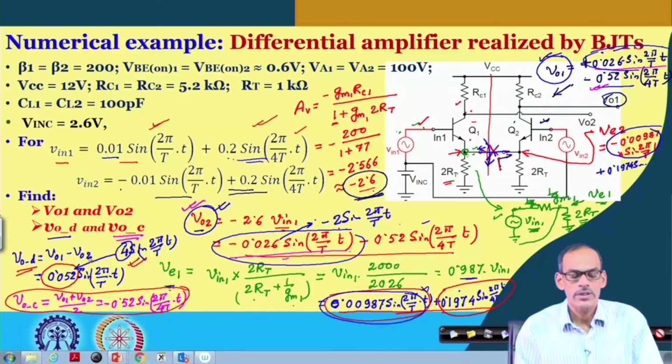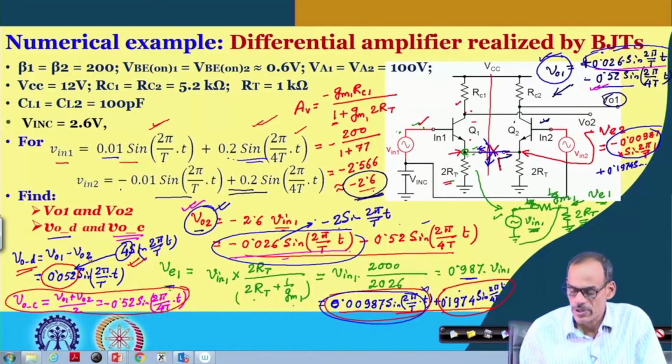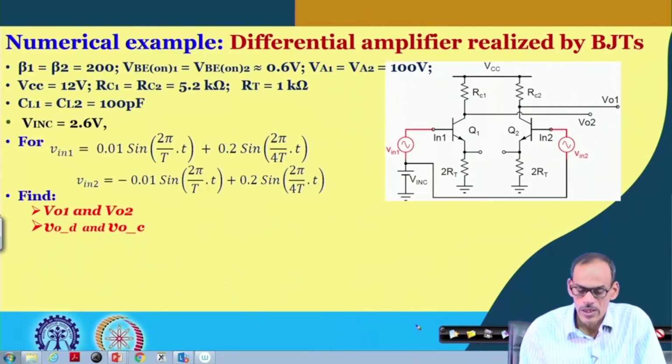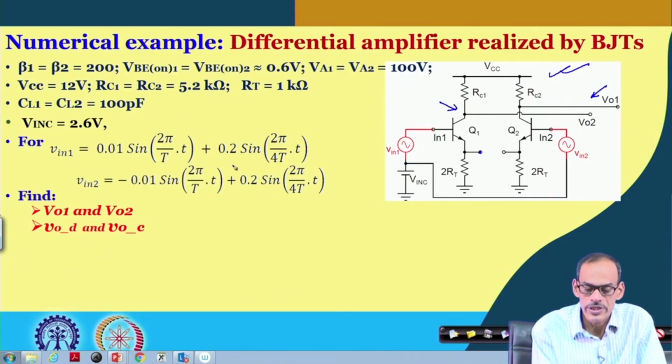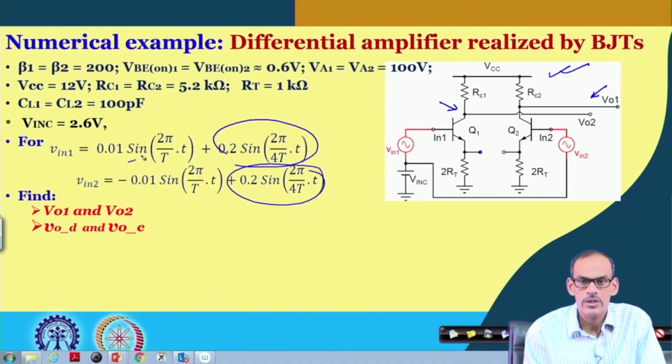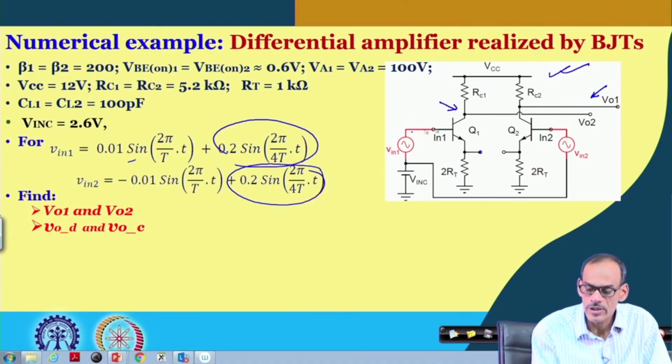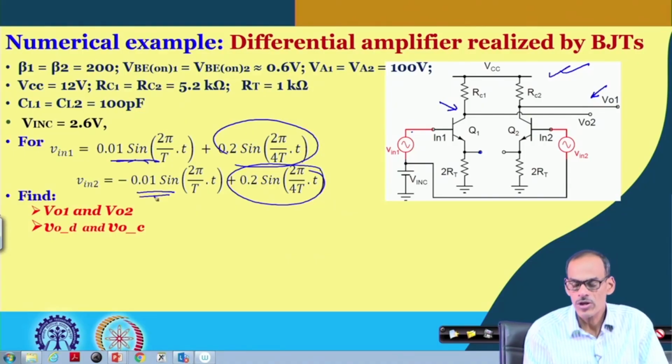In fact, in hardware you can make this experiment, namely you can construct this circuit, and if you keep it open and observe the signal here and here, mostly the common mode signal will be dominating, and hardly will you see the information from the differential part, because at the input the strength of the differential signal is very small.